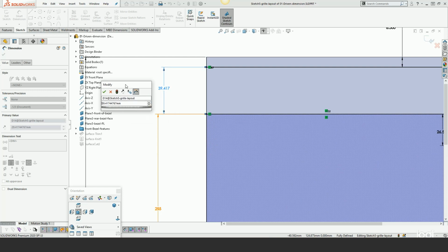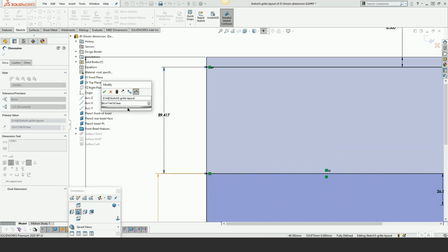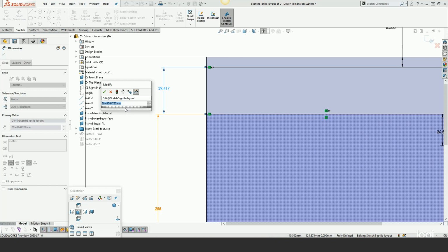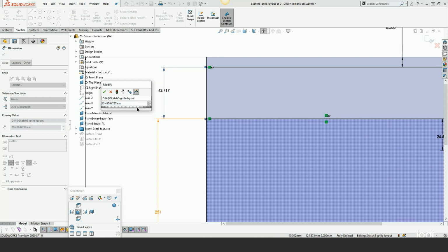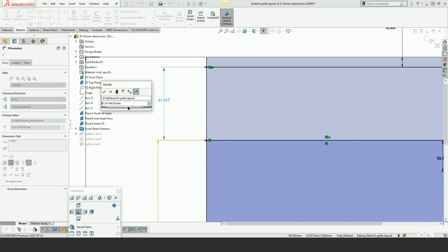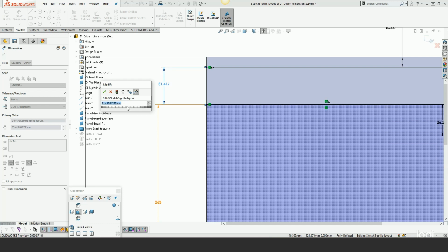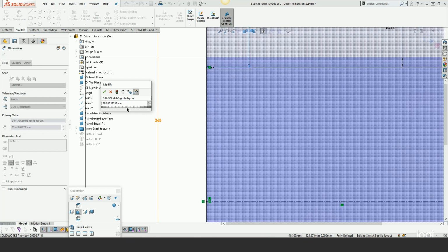Let's get this out of the way so you can see that. But if you hold down your Alt key, it divides that spin increment by 4 and gives you much finer control. If the standard spin increment is not adequate, you can hold down the Control key and multiply it by 4. So then you get some really wild gross movements.